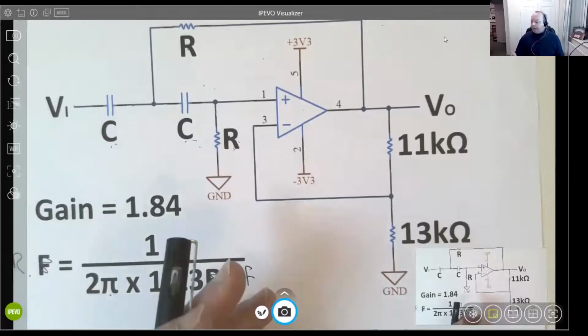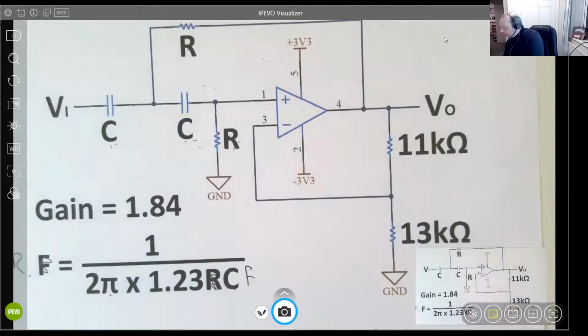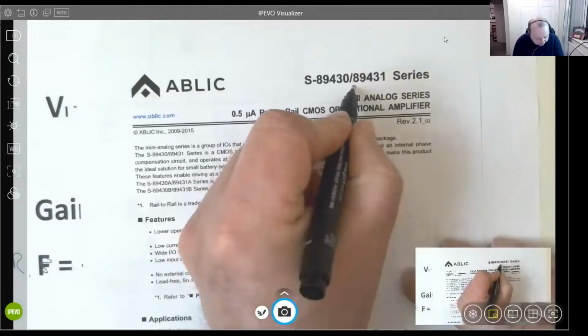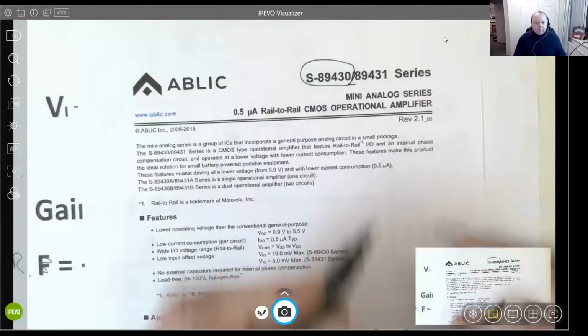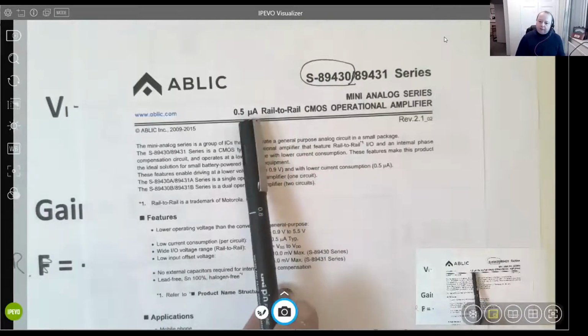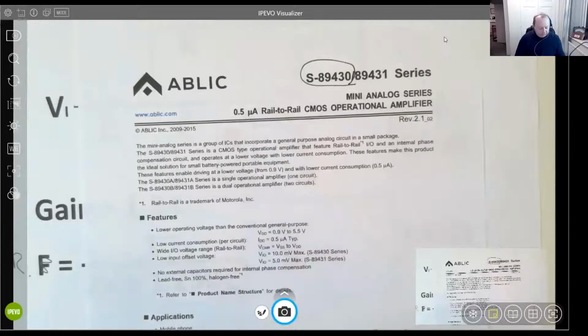There are some devices. I mean, this data sheet example. Where was it now? Yeah, this one here. I think it's that number there. Don't ask me how they come up with these numbers. But this device here, I used on a battery-operated device, and because it was such a low current device, 500 nanoamps, I actually had resistor values of, I think, 1 megohm. So it does depend on the device for sure.